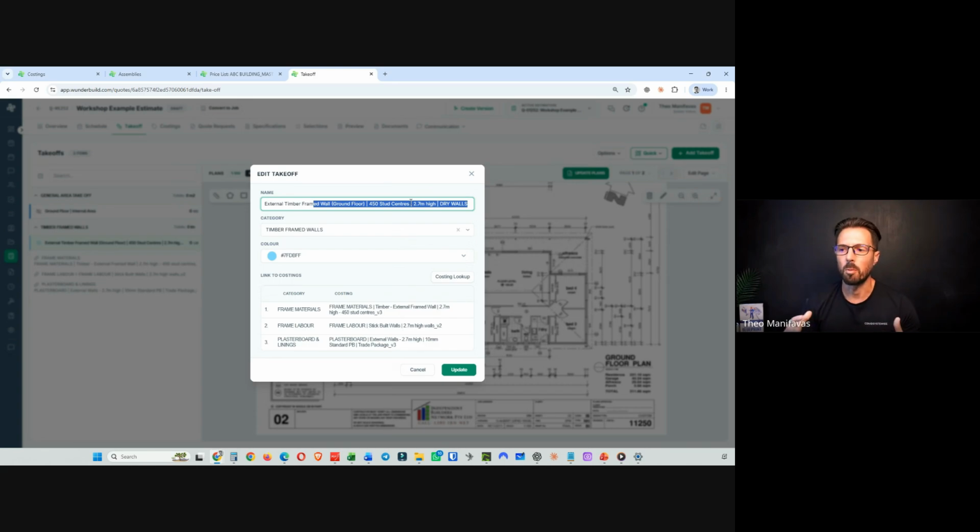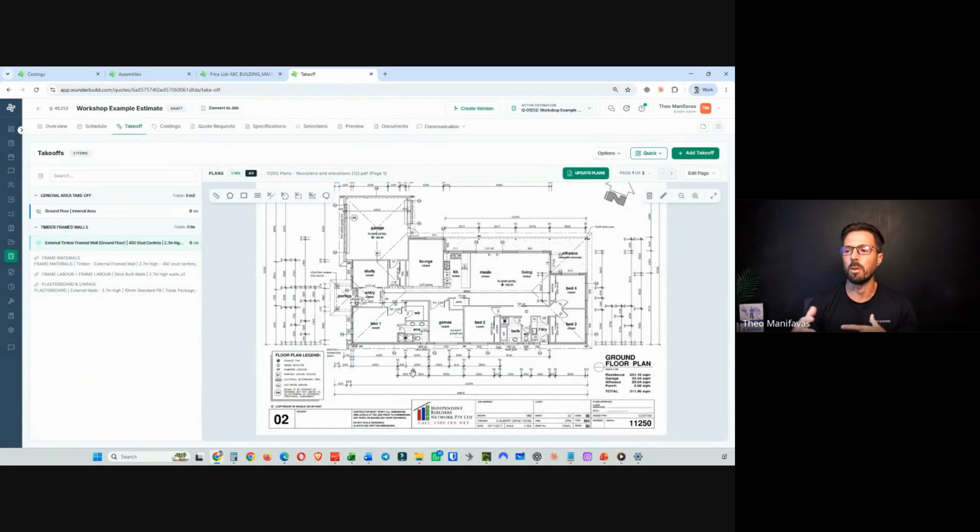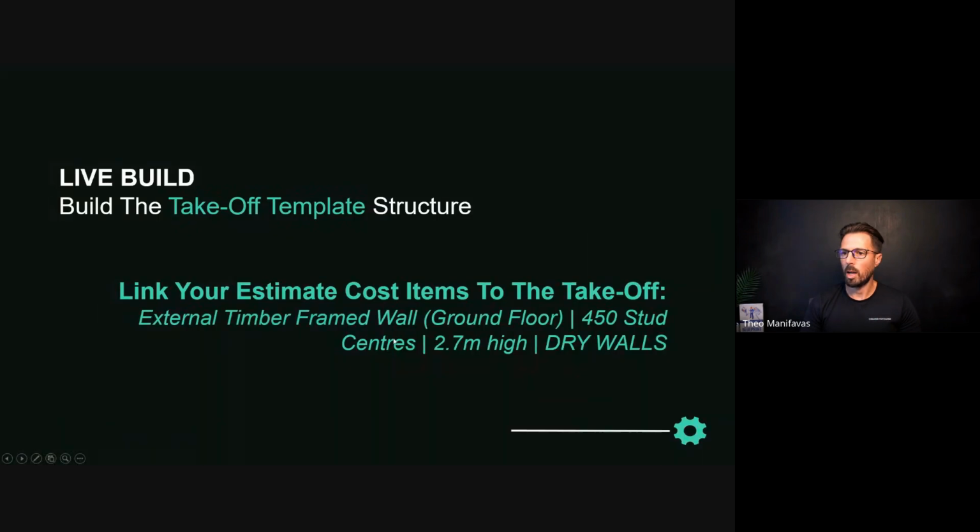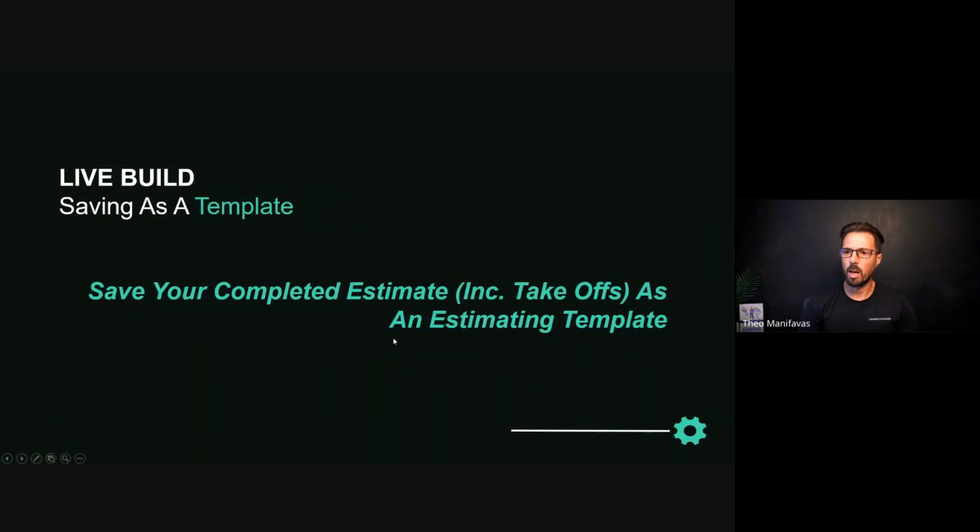So when we do this takeoff, I'm not going to measure the wet area walls again, because that's going to bring in the same thing as with the ceiling, where if I run across that wet area wall, and that wet area wall needs WR board, it's going to automatically pick up as 10 mil standard board, and then I'm going to have to go in and do deductions. And again, that just adds a layer of complexity, which can be avoided just by doing a quick little separate measurement when you're at this stage. All right, so we've linked those up.